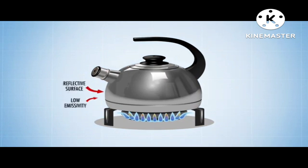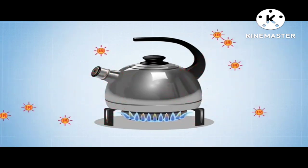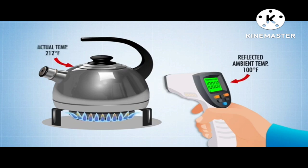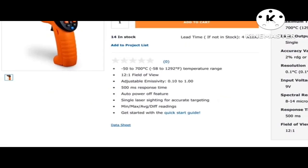Highly polished metals typically have very low emissivity ratings, since they tend to be very reflective of ambient infrared energy and less effective at emitting their own electromagnetic waves. If you point an infrared thermometer with fixed emissivity at a stainless steel pot filled with boiling water, you might get a reading closer to 100 degrees Fahrenheit than 212 degrees Fahrenheit. That's because shiny metal is better at reflecting the ambient radiation of the room than it is at emitting its own infrared radiation. Some industrial infrared thermometers come with adjustable emissivity settings, so you can more accurately compensate for the type of surface being measured.